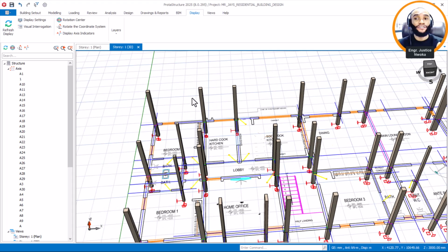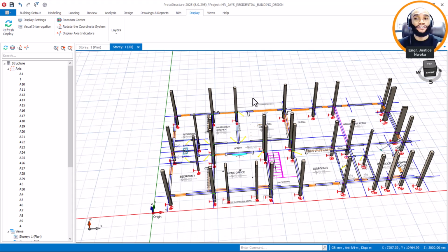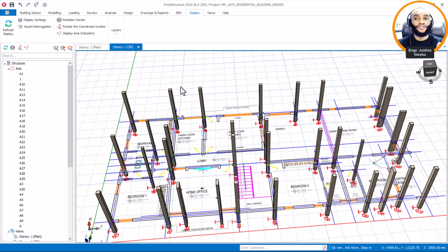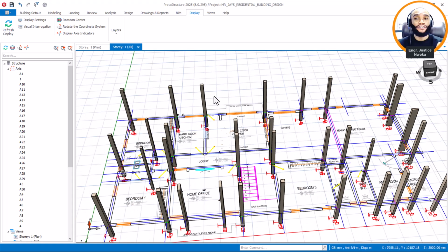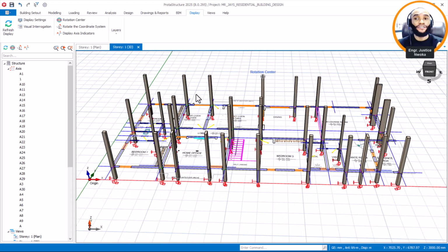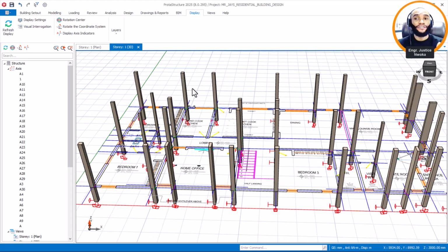Okay, we will have to change all the other ones too to make sure they match directly the way we have on our CAD file. But if at all we want to name a new grid line, which is the structural grid line, then we can begin to assign a new grid line which will be useful for the structural drawing during the construction. That's fine. So with this, let's now move on to the beam insertion method.